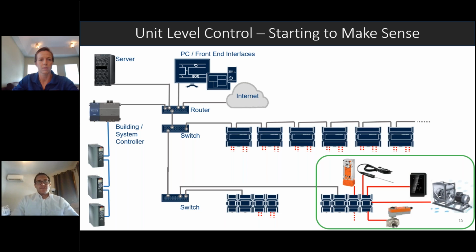So what we would like to see is to have all those VAV boxes and the air handling unit that's serving them all be networked together on a BAS system. With that, you're going to be able to do some system level functionalities that you wouldn't be able to get with them all being standalone. That main one would be fan pressure optimization.